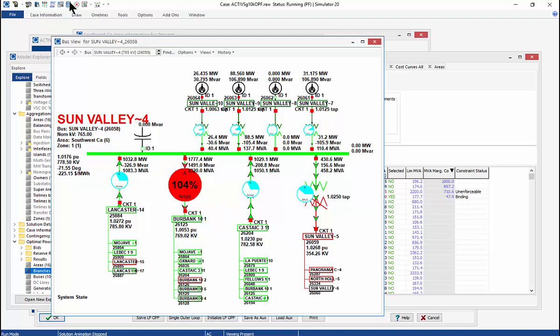You try taking this offline. I don't know if that's going to cause this to blow up or not, but the overload goes away on that. The voltage still seems kind of reasonable, but it's still missing the target. So it might be a faulty set point, or maybe this voltage dropped here too, I think. Anyway, it's a voltage related overload. We still have a pretty low power factor on this line.